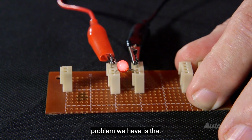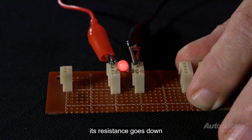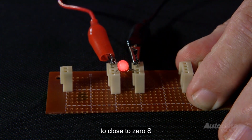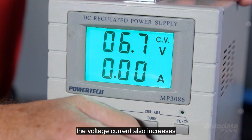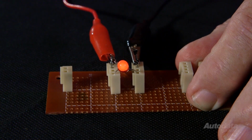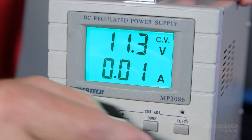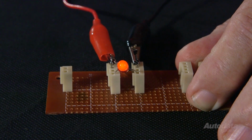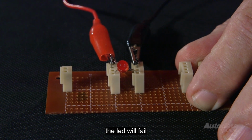The problem we have is that when the LED starts to conduct, its resistance goes down to close to 0 ohms. This means if we increase the voltage, current also increases. And if we increase the voltage too much, the current will reach a point where the LED will fail.